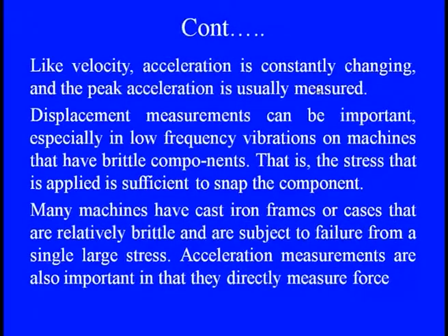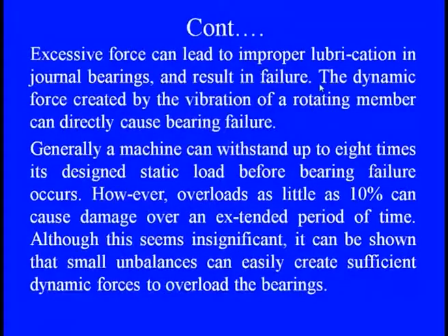So, acceleration measurement is also one of the important features, because it measures the force part, that is, how much inertial force is there when the mass is rotating. Excessive force can lead to improper lubrication in various bearings or gears, resulting in failure. Dynamic forces created by the vibration of any rotating member can be directly measured using the acceleration of that rotating mass, and we can find out how much these inertial forces are, which can cause failure.